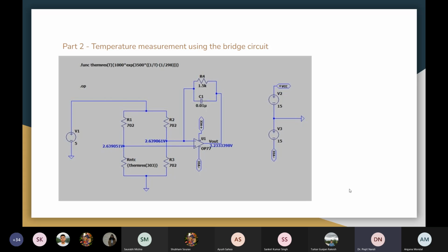But when we are powering up the chip, like when you power up the TV or your computer, there is a certain settling behavior because of power up. What would have been interesting to observe from the class is somebody doing a transient analysis, maybe showing V1, the 5 volt bridge power supply, ramped from 0 to 5 volt in, say, 100 microseconds.